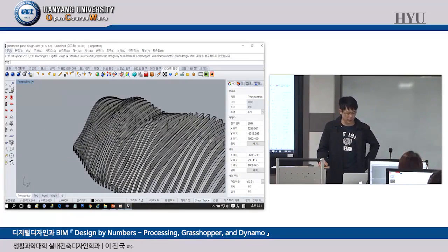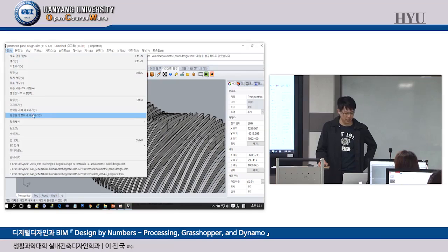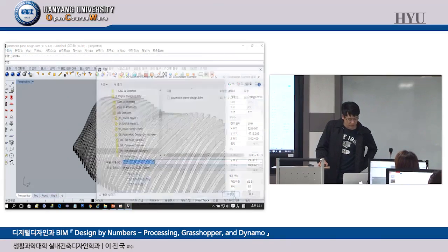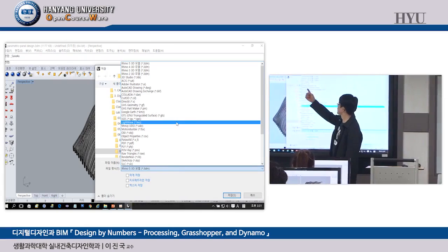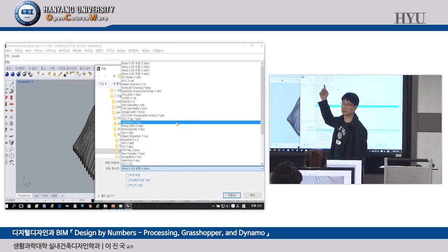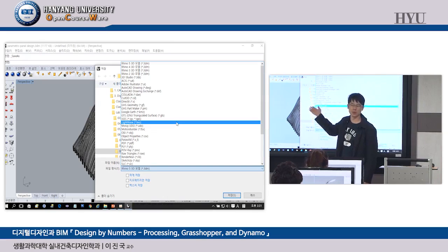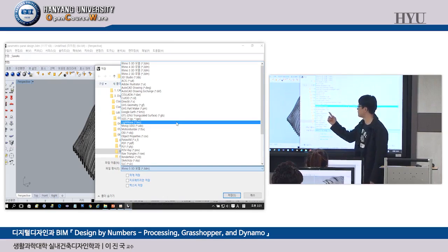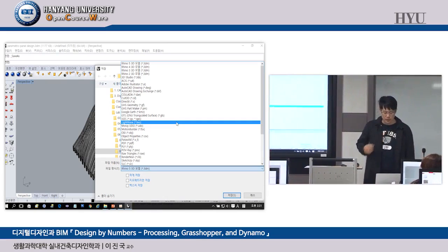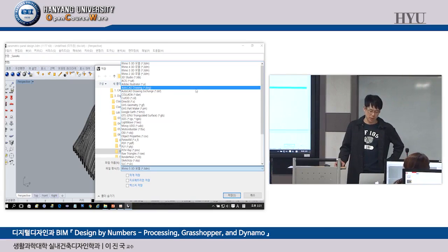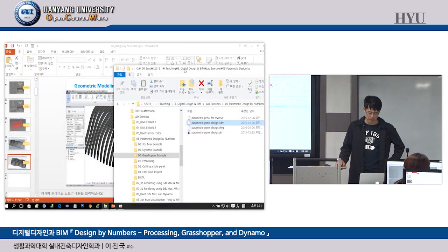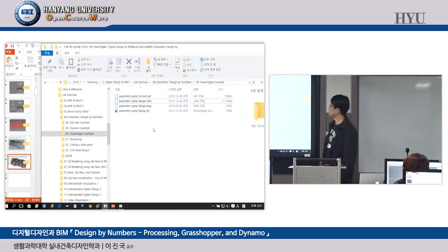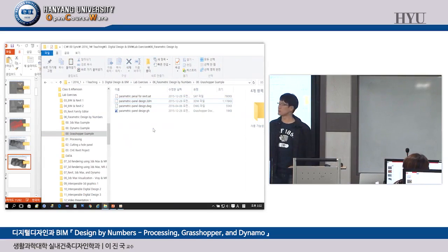In this Rhino, you can save as, export, okay? You can save as in very different file formats. So SAT file is one of the standardized, representative industry standards for solid 3D geometry. As you know, DWG, FBX, they are all other famous 3D model file formats, but they are just surface-based 3D. We already stored the file, so let me close and take a look at those different files.